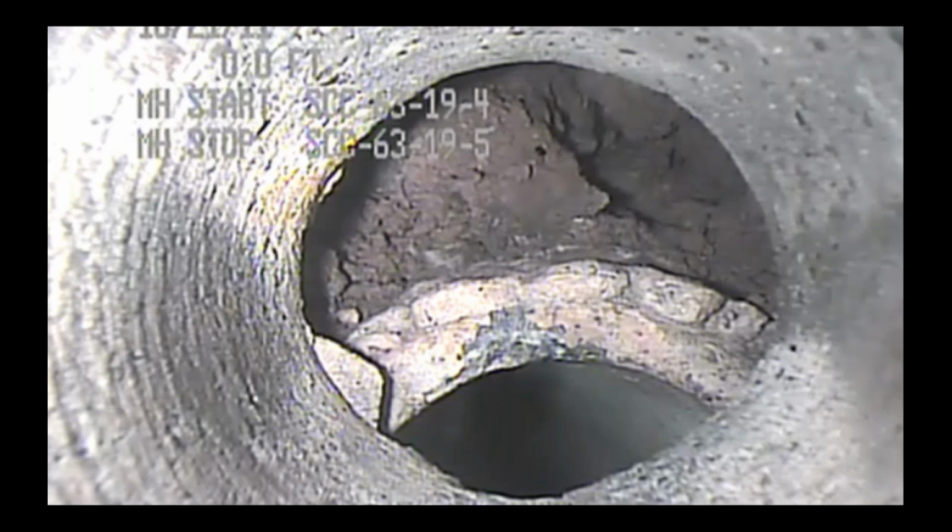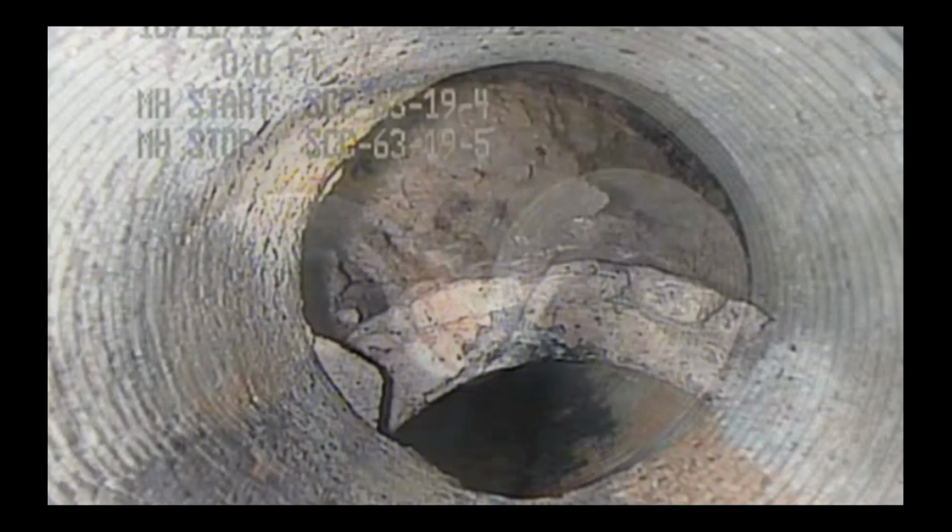So as the embankment settles, it can push the conduit and it can actually shear from the riser structure, which is sometimes built on bedrock. So it really can't yield at all, and you'll get a concentration there. The same thing can happen with an anti-seep collar because it's more rigid at that location and less compressible.